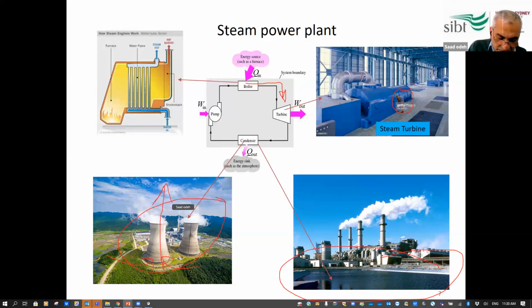And in the other way, we spray the water coming from the condenser inside these towers to cool it down by air. So when we cool it down, we collect the water at the lower temperature at the lower part of the towers. Okay, so it's a bit complicated operation here, but just to give an idea about the steam power plant. So if you see this in the future, you understand how it operates, at least in general operation of this plant.